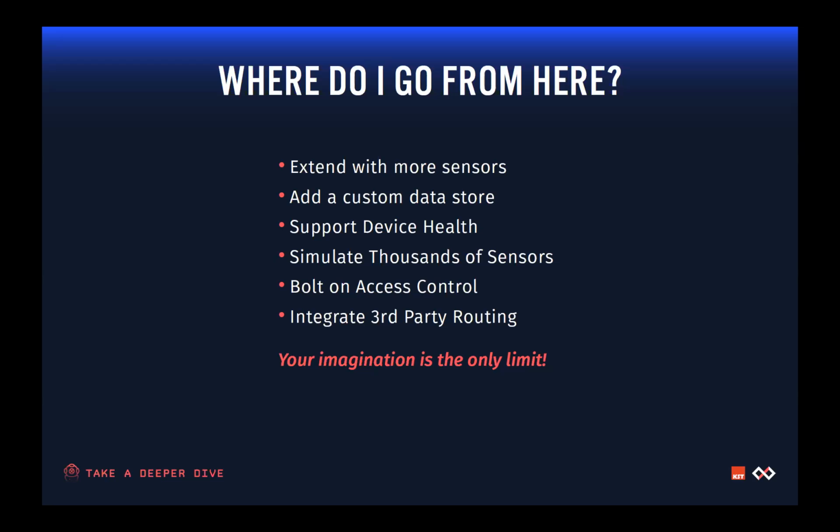A lot of our customers also care very deeply about the health of the device once we deploy it. Devin showed you how our application template has this idea of signal to noise ratio, or SNR, and RSSI. We use that data to determine whether or not those sensors are healthy. So you might want to come up with your own algorithm. Maybe you want to say if the SNR changes by more than, say, 15% in a device that is not supposed to move, maybe that's an indicator that a base station changed, or maybe our device is moving. Or maybe you want to look at RSSI, and if you see a 20 dBm difference day after day, that may be an indicator of something wrong from a device health perspective. So you may want to bolt on your own health API to make sure that the devices are healthy.